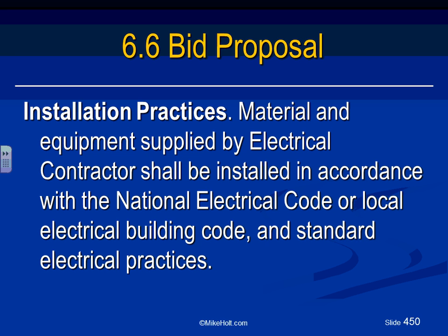Installation practices. This is just covering you if you bid a commercial job and everything you're doing is in EMT. They didn't say the wiring method. You're doing the common practice for a commercial project, EMT and MC cable. Now you walk into somebody, let's pick on Wisconsin, and the guys in Wisconsin want you to use rigid. Well, this is not common practice in commercial. So that's how you cover this.